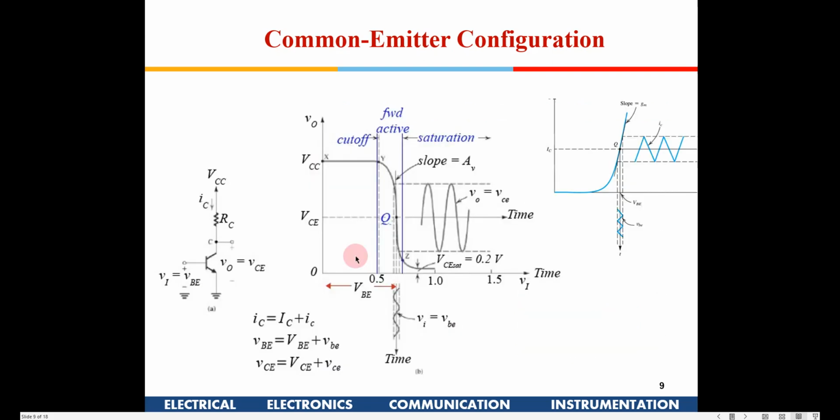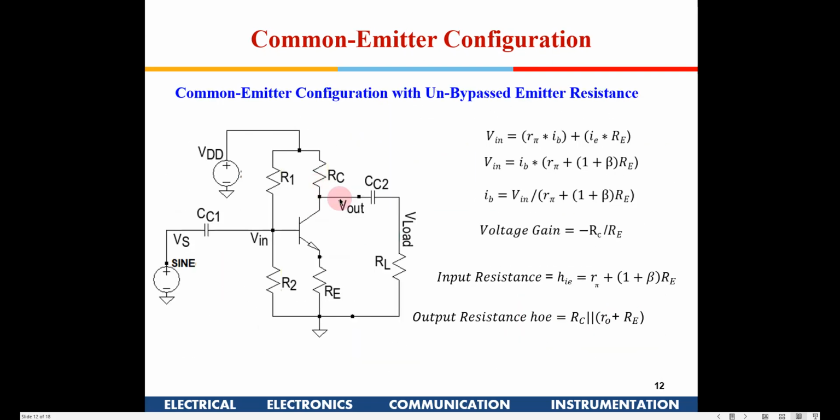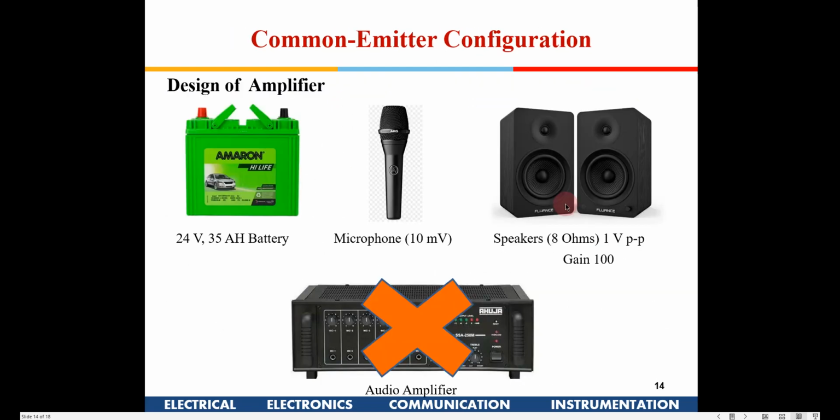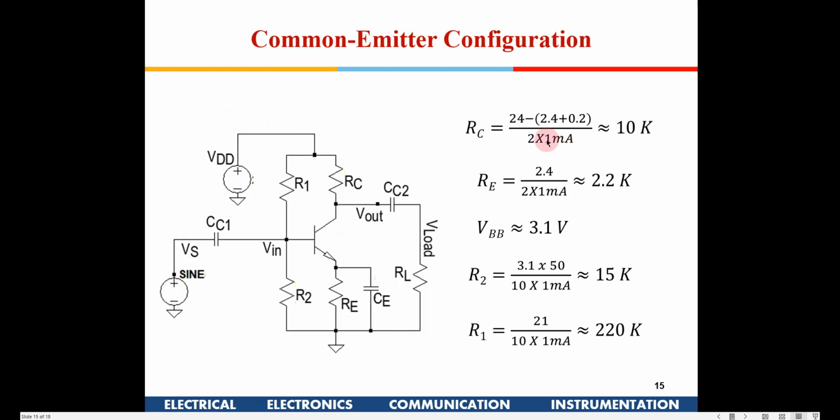That depends on the specifications of the particular transistor. You have to see the data sheet and target the value, and you have to decide the value based on your power budget. Now here in this particular case, I have taken a 1 milliampere current which I am going to allow to flow in this transistor. Okay, so I have taken 1 milliampere.